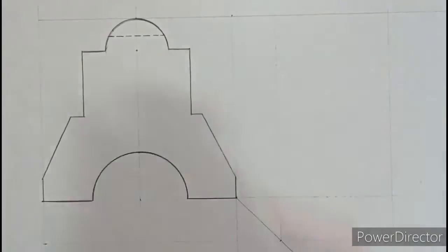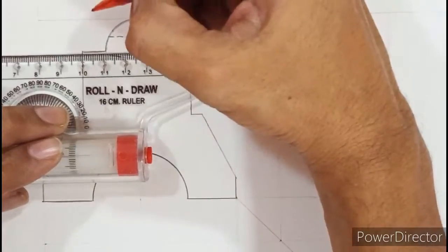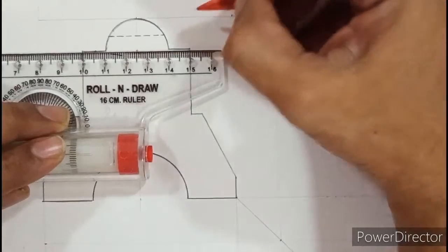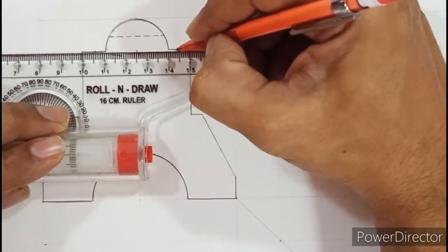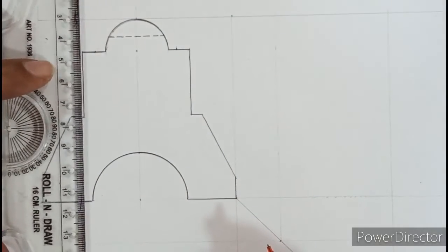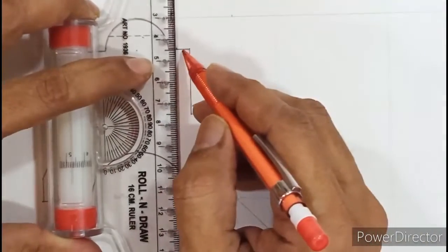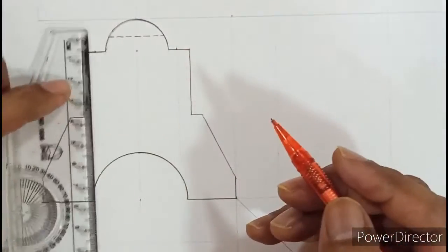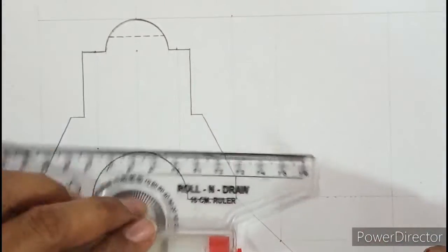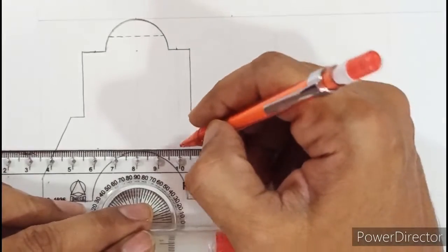So over here, from this shoulder, you need to move in by 6. So let me mark 6 millimeter. On one side or both the sides? Yes, it's on both the sides because of the symmetrical nature of the object. Now once you mark that 6 from here, you need to go inside and come down by 45. So let me mark 45. Yeah, so this is 45, and the same 45 I need to mark on the other side also. So I'll mark the same 45 here also.